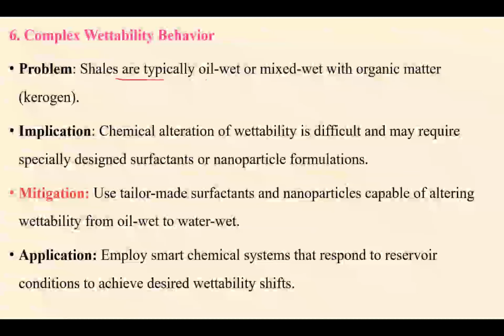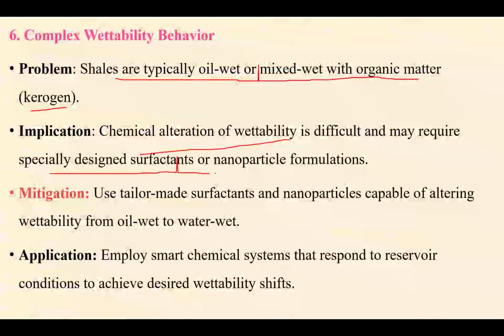Now the shales are typically oil wet. Okay, that is another challenge, or mixed wet with organic matter, that is the kerogen present, as you have learned. So chemical interaction to alter the wettability is difficult and may require specially designed surfactant or nanoparticle formulation.